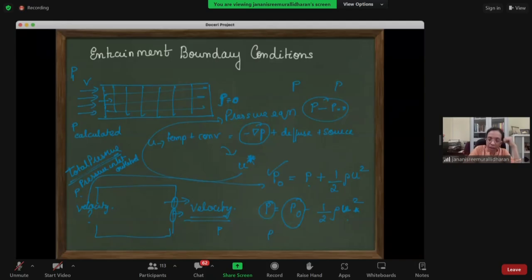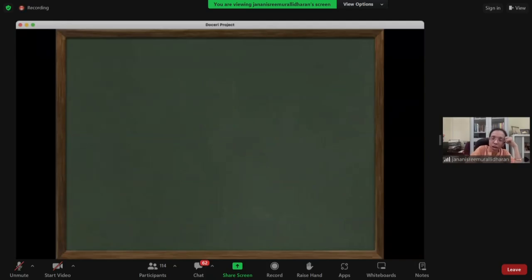Now, if I have temperature driven flow, coming to natural convection, I have a system which is heated. So this is my domain, with dotted lines, and this is the atmosphere. I have no clue what is going to happen at the openings, but I do know that this is going to be driven by hydrostatic difference, rho g h. So I use something called p_rgh total pressure. There's a version of p_rgh pressure also, I think, but there's no big difference.